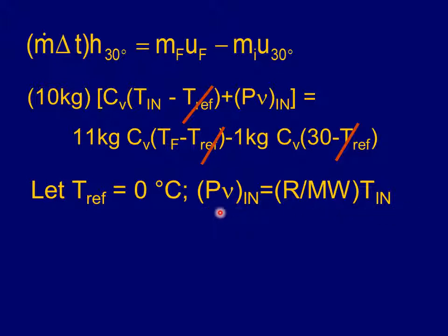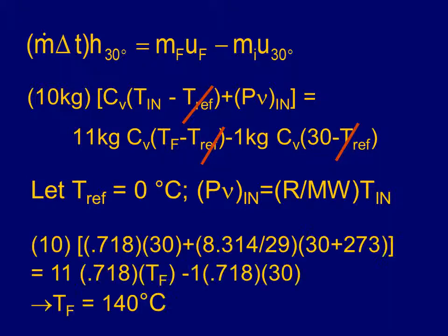However, we have to be a little bit careful here, whereas up here we're using degrees Celsius, this Tn has to be in degrees Kelvin because we're solving it from the ideal gas equation. Little subtle. To be honest, this problem is probably easier just putting everything in Kelvin and solving it that way. So I would recommend that you try it that way and see if you get the same answer.